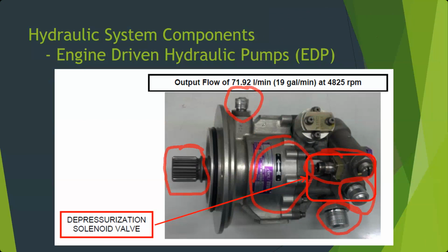Okay. One other item that you can see on here that we couldn't see on the last one is if this pump were to fail, we don't want it to damage the engine or bog down the engine. You can see they've made the shaft thinner. There's an area where an O-ring can go, and then the shaft gets thinner down in here. That's so that the spline portion can shear off. So if the pump gets jammed and the engine wants to keep spinning, it can shear that off and break it off and allow the engine to continue to operate.